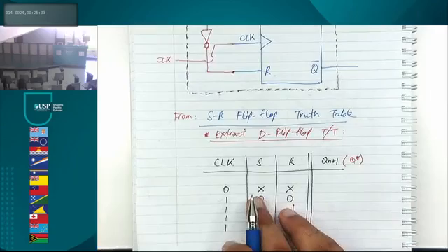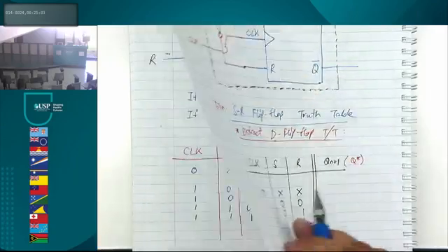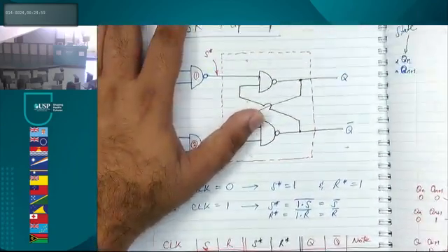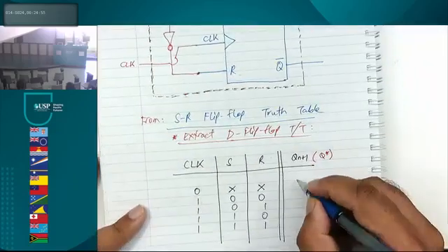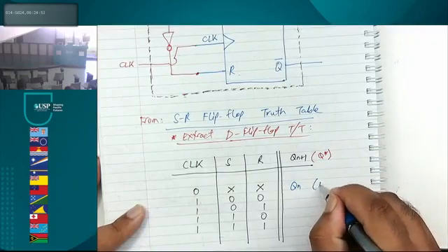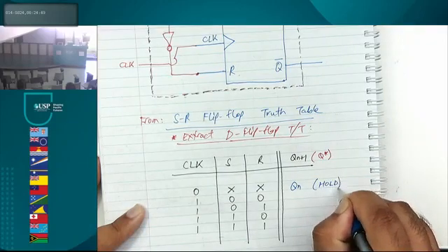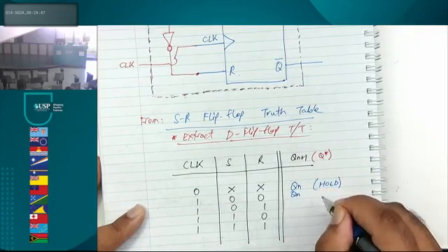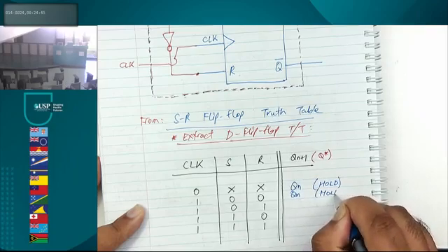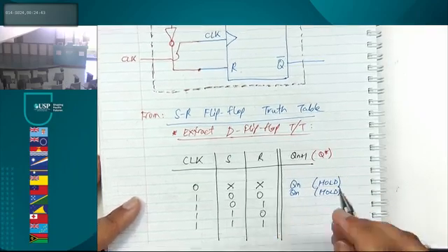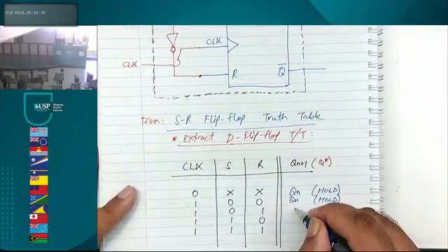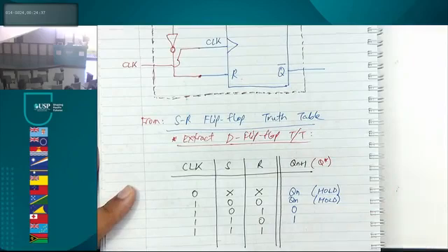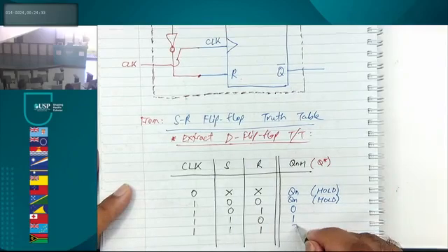And then we say, hey, whenever the clock is 0 in this case, in our earlier case, right? I'm just rewriting, okay? I'm just copying. We said there will be Qn because it's in hold mode, right? Again, this will be Qn, which is hold mode, right? 0, 1, 0, 1, the Qn plus 1 was equal to 0, 1, 0, 1. And we said this guy was invalid.